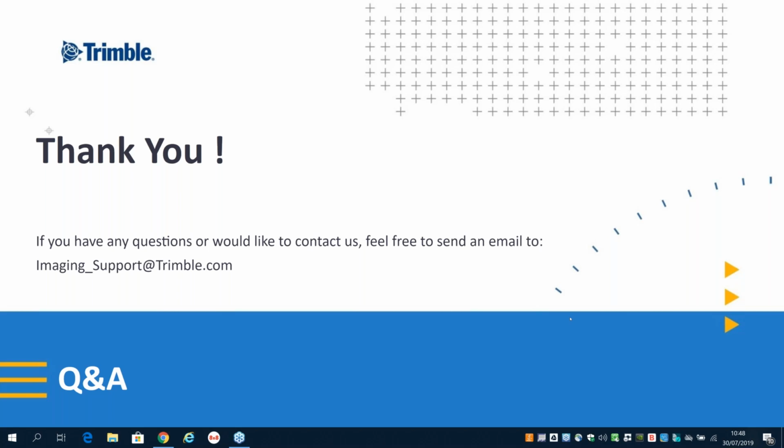Well, I would say this depends on your speed. How fast you can drive when you cover 1 kilometer depends also on the system and the point density you're using or you're willing to have at the end. So you could drive slowly, then you get a much denser point cloud, but also with the MX9, covering lots of data at a very high rate, I think you'd be okay driving fast.